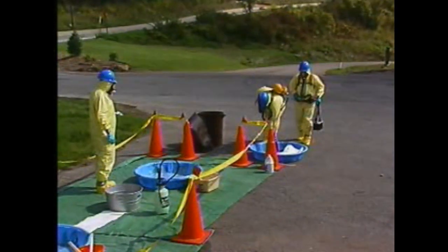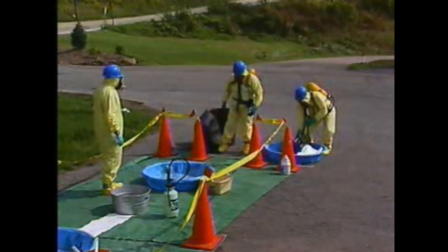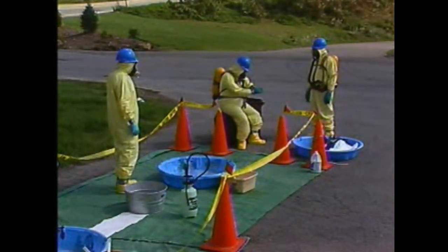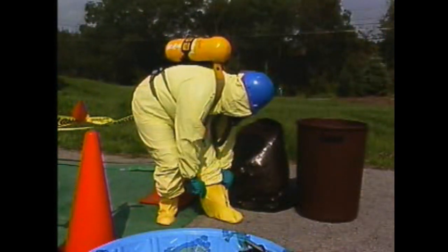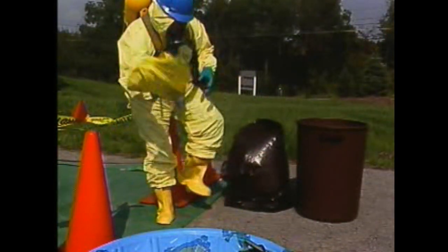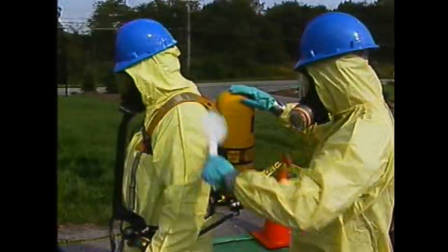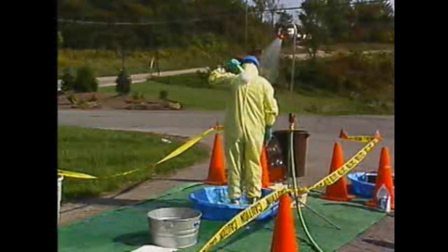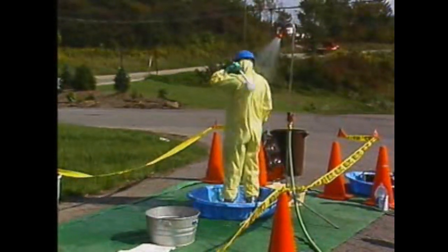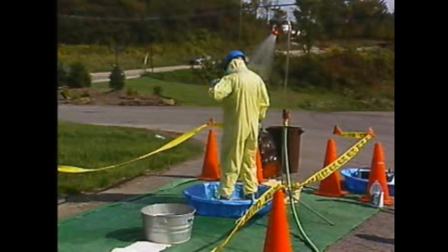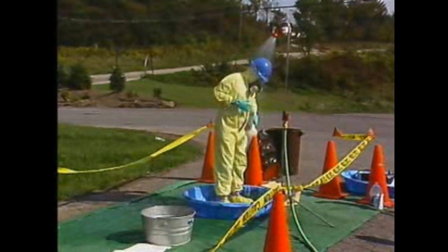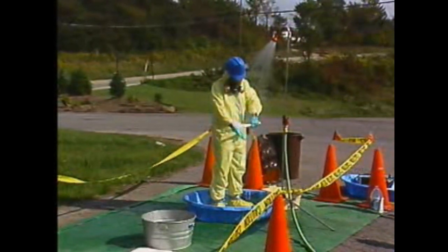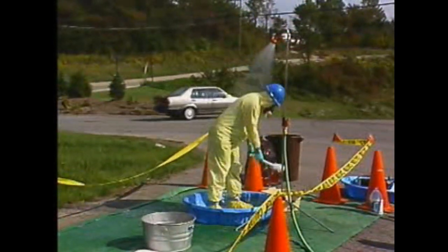When the job is complete and you're ready to remove your protective clothing, be sure that you follow proper handling procedures for the contaminated clothing. Clothing that was exposed to certain hazardous chemicals will have to be carefully disposed of, and other clothing may require special treatment to remove contamination. Some types of contamination even require you to shower before you enter a non-contaminated area. Be sure you know the hazards and follow approved procedures for handling protective clothing that has been exposed to a contaminated area.